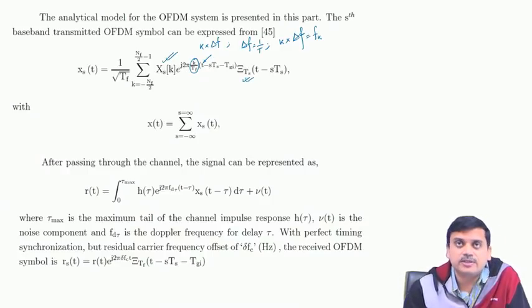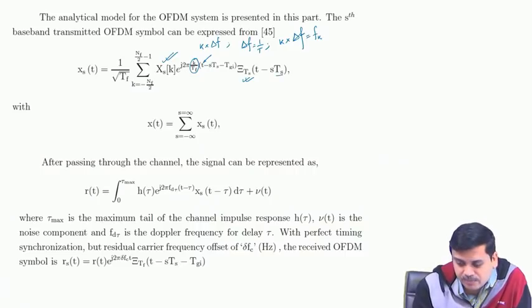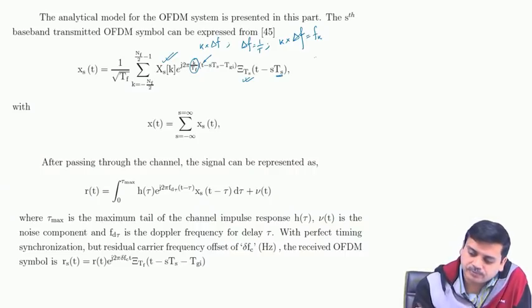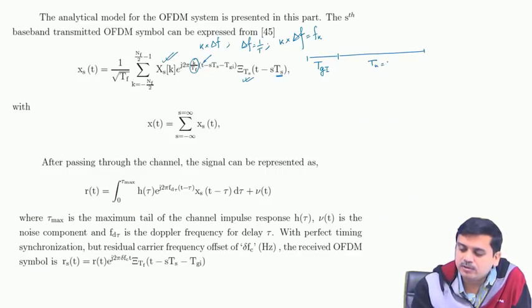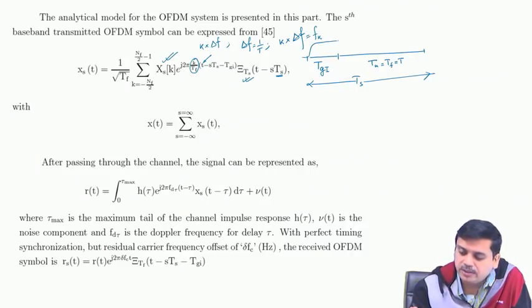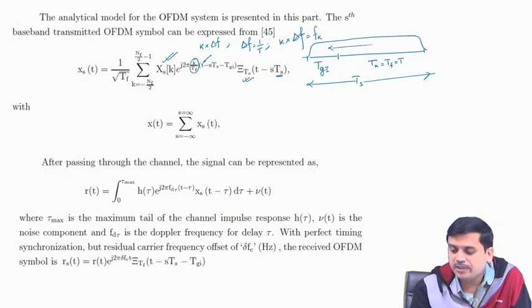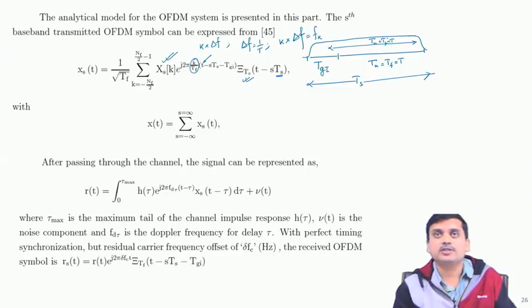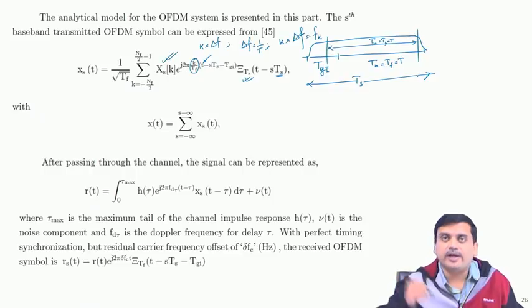This is the gating pulse, we said it will be rectangular, but since this pulse is stretching over time T_s, and T_s is, since you have seen the guard interval T_GI and T useful, sometimes written as T_f, and as per our earlier notation it is T. So, this entire duration is T_s, and one can easily do a pulse shape which is not rectangular but slightly tapered at the end, ensuring that the duration T_u equal to T_f equal to T as per our notation is rectangular. So, in this period one will find it rectangular.